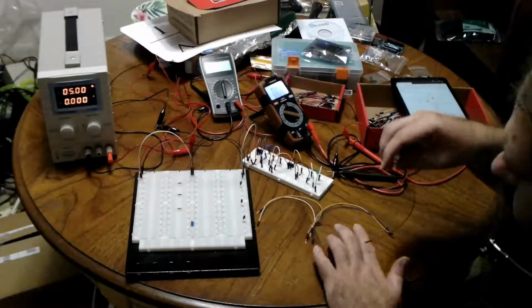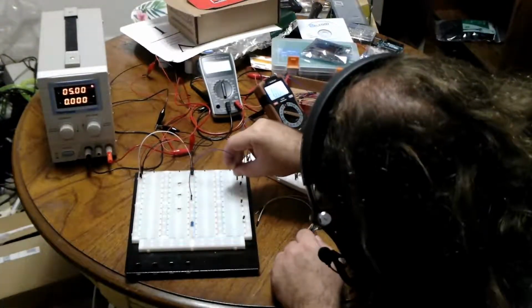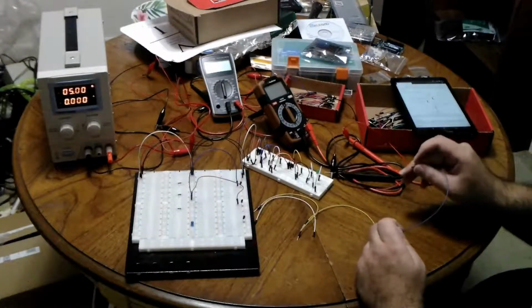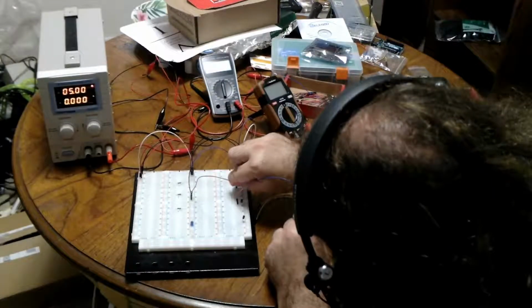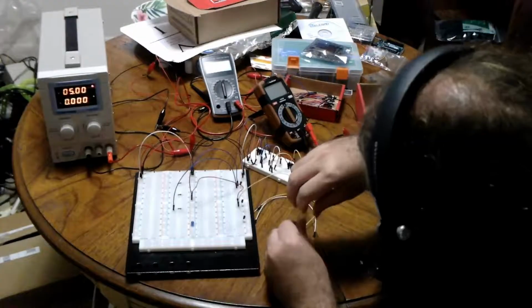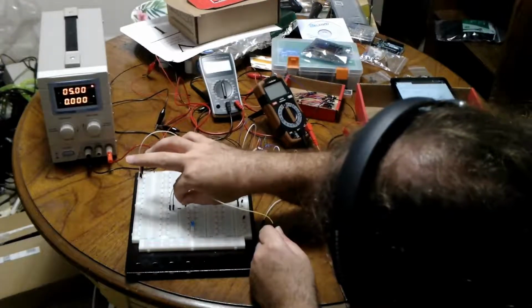So for the OR gate, both transistors are directly connected, their inputs with positive power. So that's 1 and that's 2. Their outputs are similarly connected. So we have output 1 goes through to a resistor. Output 2 goes through to the same resistor on the same side. And that resistor connects to negative power. We'll just use that one.